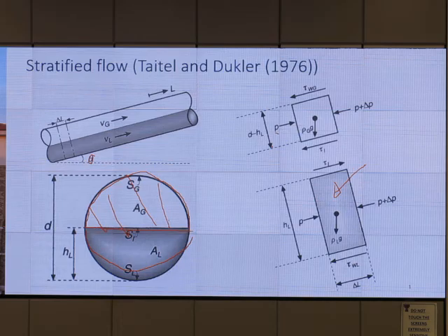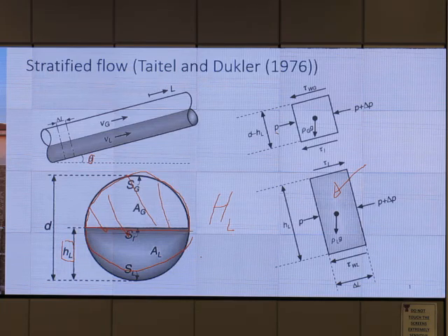Let me ask you: small h sub L, and capital H sub L, are they the same? Yes or no? No. Are they very different? How close are they? Small h sub L divided by capital D. Okay, I'm sorry, so this is the ratio of the liquid height per pipe diameter. This is almost capital HL, but they are not the same.